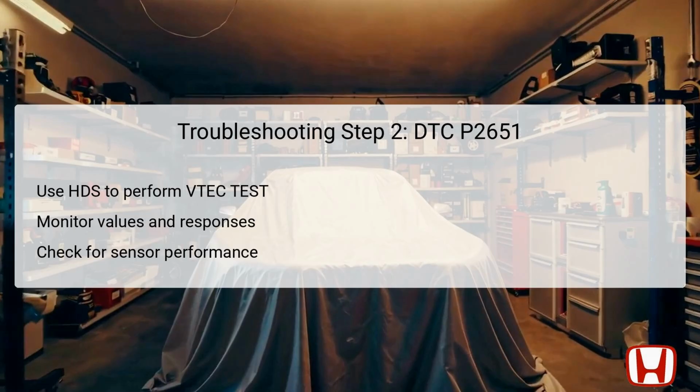If the HDS indicates that the sensor performs outside of normal ranges, it may confirm that the rocker arm oil pressure sensor is faulty. Performing this test not only validates the sensor's functionality, but also pinpoints potential issues within the system more effectively.